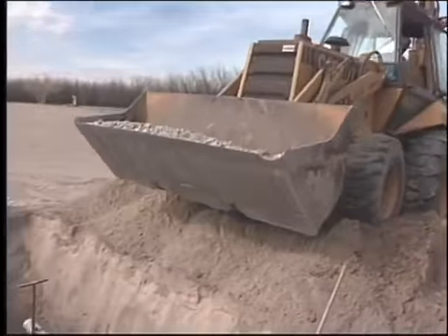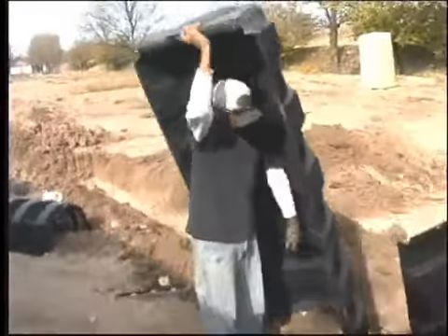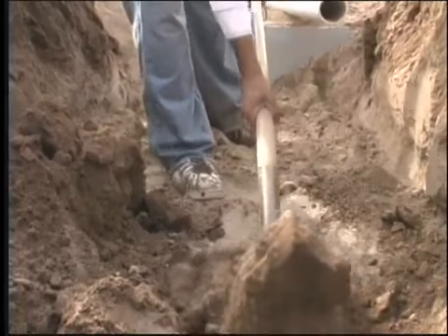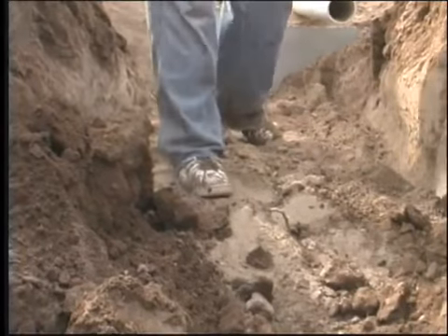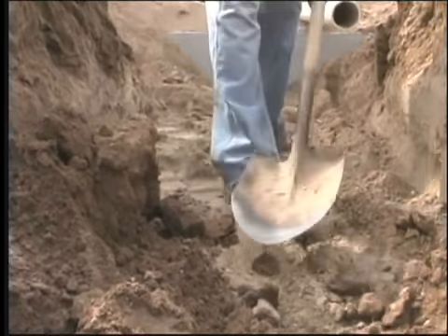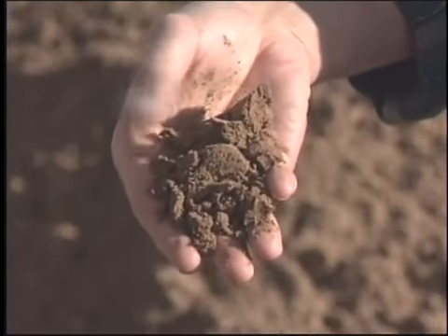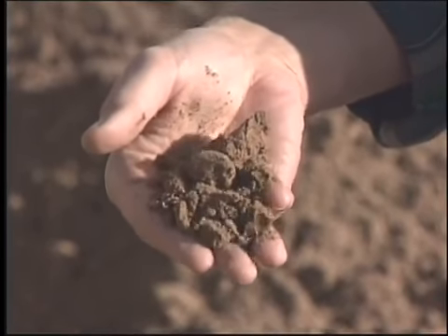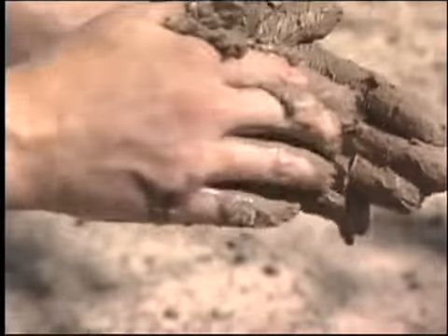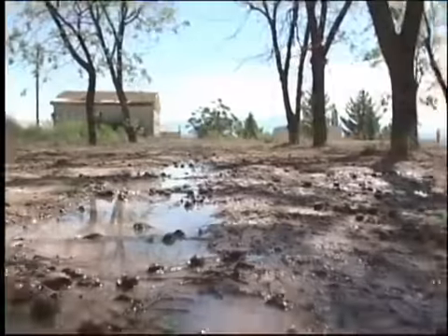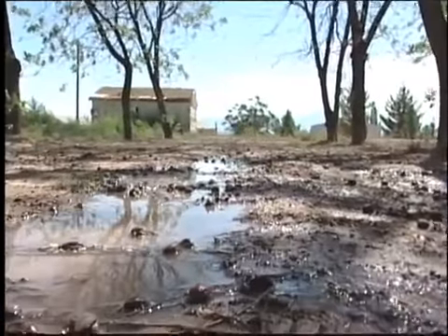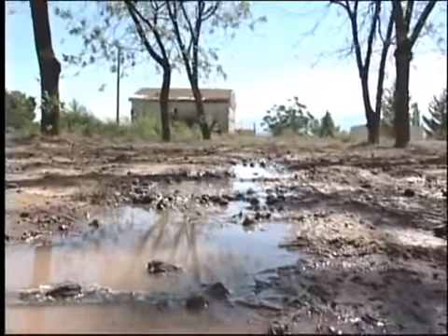The two most common types of drain fields are the gravel and pipe drain field and the chamber drain field. Both drain fields require digging a trench, which will contain the distribution system. In clay soil, the trenches for the drain field should be only dug when the soil is dry and crumbly. Smearing and compaction due to construction in wet soil decrease the ability to absorb wastewater.